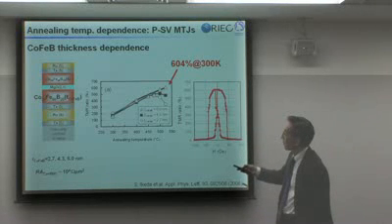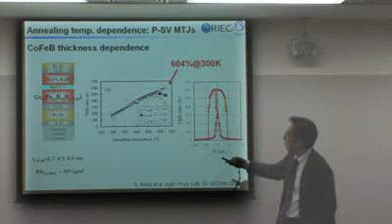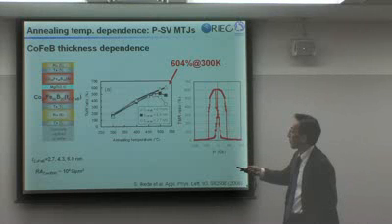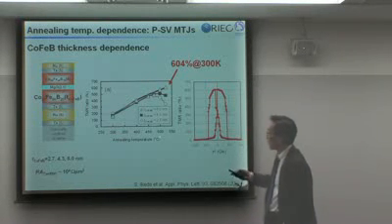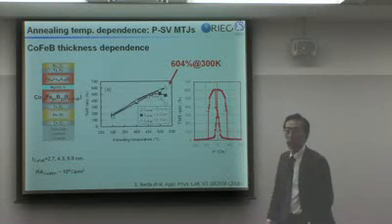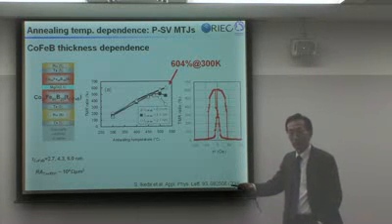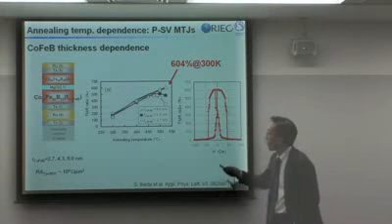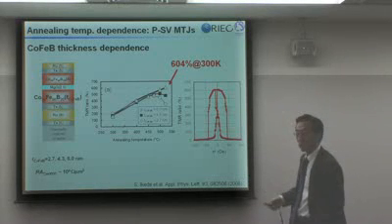In order to show that tantalum is doing something detrimental, we made this cobalt iron boron layer thick and reduced the tantalum diffusion, and we have shown that even at a very high annealing temperature, we can get 600%. Although this is not exactly the structure we are going to use for integrated circuit applications, this shows clearly the potential of the structure that we are dealing with.